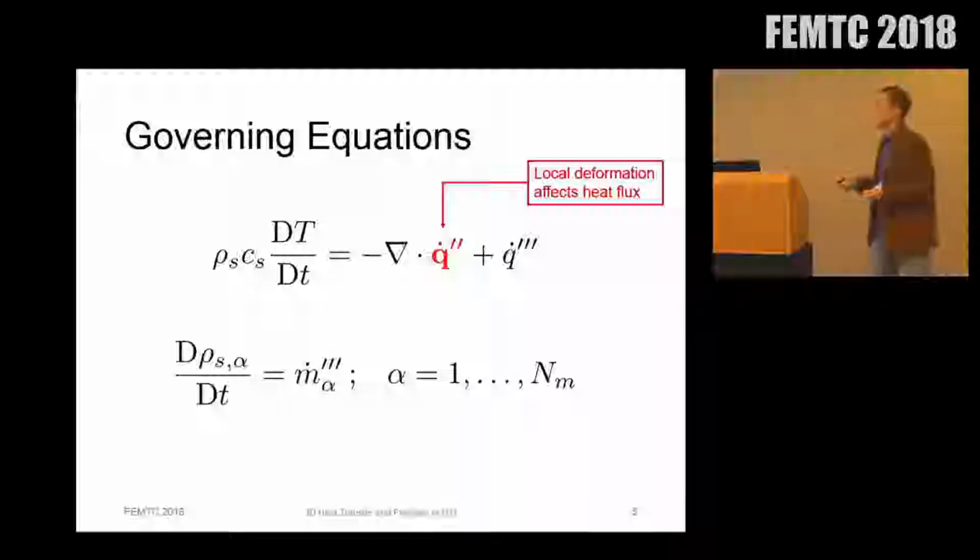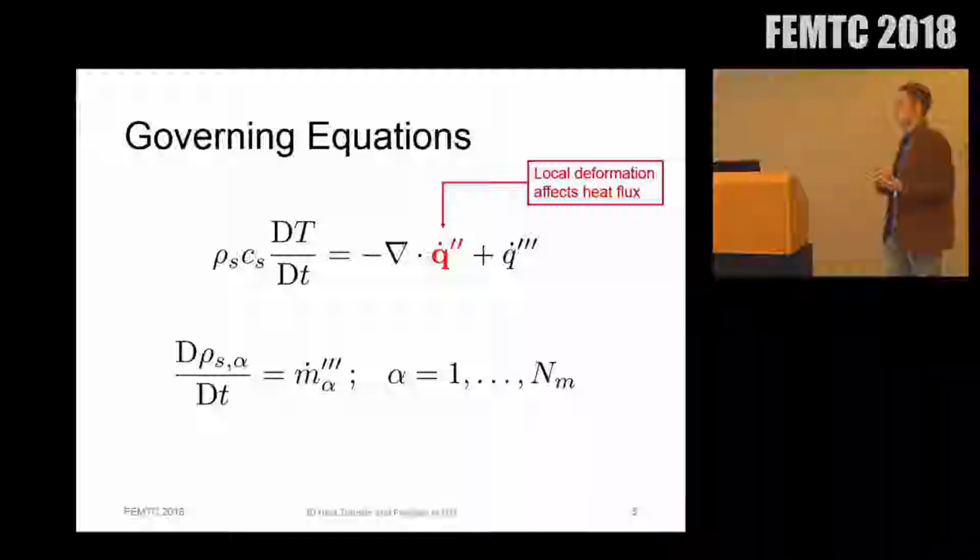There should be a gasification term here, but I also point out that a lot of the times the way you see these pyrolysis equations written down is also not correct. You'll just see a partial derivative here, and that, strictly speaking, isn't true. And I'm not sure that I've actually seen the correct equations written down for fully three-dimensional heat transfer and pyrolysis with multi-phase flow.